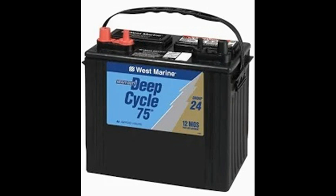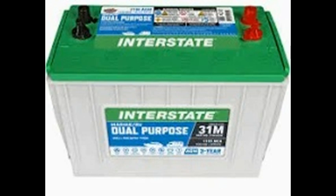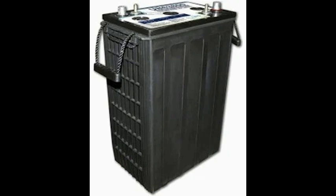Originally designed for a moderate discharge rate, but with the ability to deliver greater amp hours than a starting battery. Many deep cycle batteries today are a hybrid of a starting battery and deep cycle battery and labeled marine or RV batteries. And so they have the ability to deliver high current for a longer period of time.